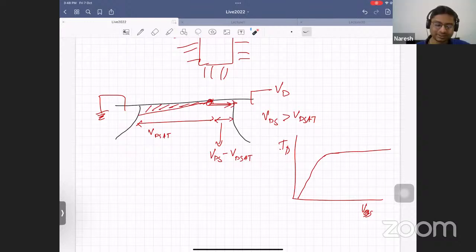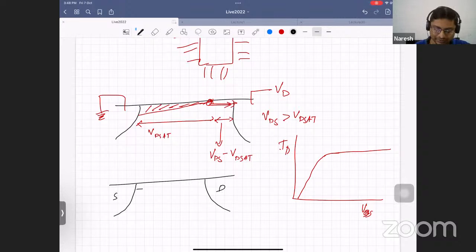Okay, this is a very interesting question. When we talk about the old transistors, let's say this is source and this is drain, we used to call it L drawn. Drawn means basically what you do in the GDS file, when you fabricate the transistor, how much you designed it to be. And your channel length was that. But because this was very, very small.